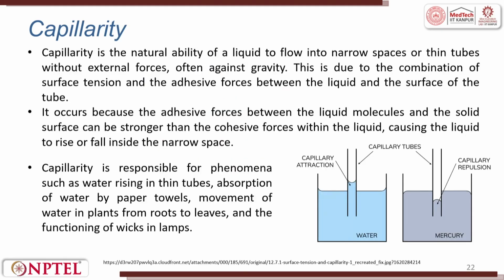Now, next concept is capillarity. Capillarity is the natural ability of a liquid to flow in narrow spaces or thin tubes without external forces, often against gravity. This is due to combination of surface tension and adhesive forces between the liquid and the surface of the tube. Whether we talk about water being absorbed by plants or ink coming to the tip of the pen or water being absorbed by towel, this is all due to capillarity.